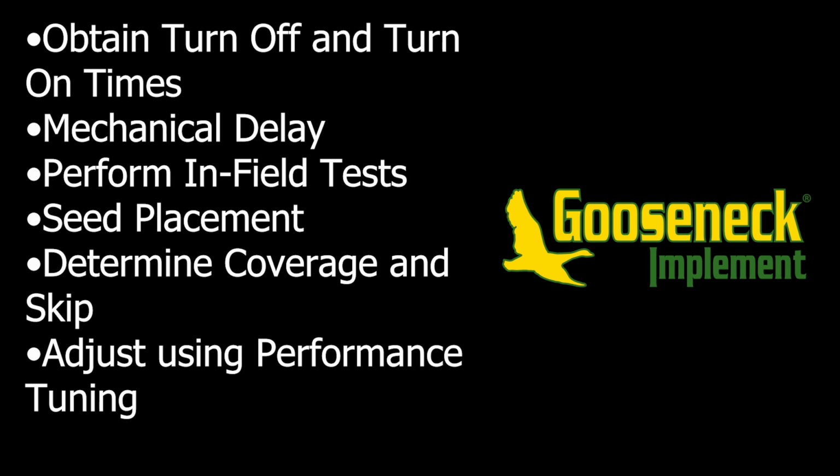In this video, we learned how to accurately obtain our turn on and turn off times for our inner and outer runs, the purpose of mechanical delay, how to properly perform an in-field test, marking seed placement, and then measuring our markings to determine our coverage or skip, and how to adjust our coverage or skip using the performance tuning application.